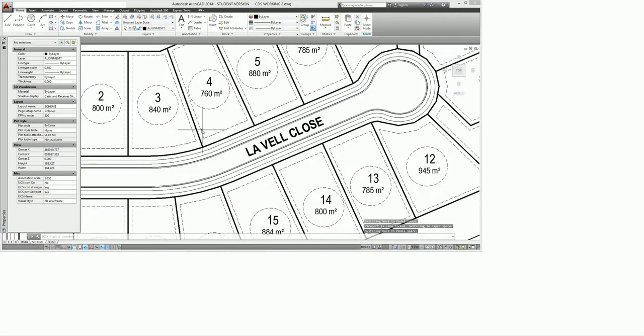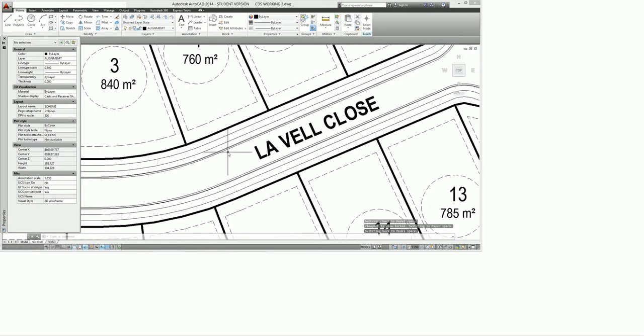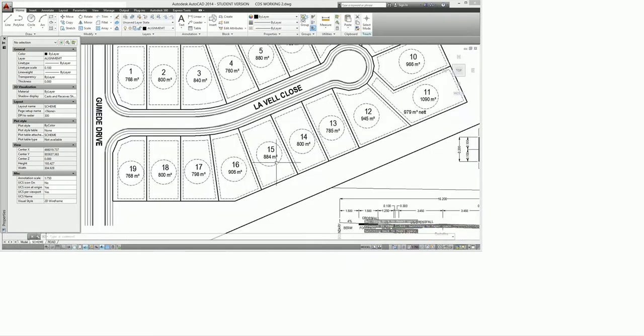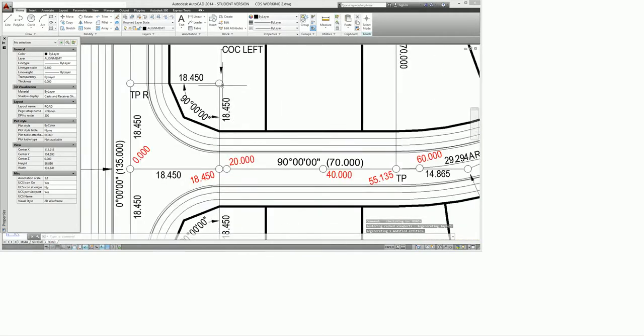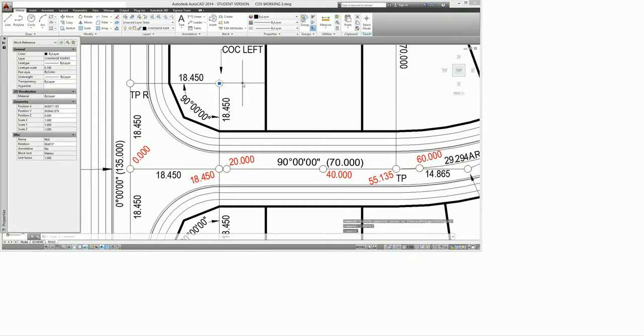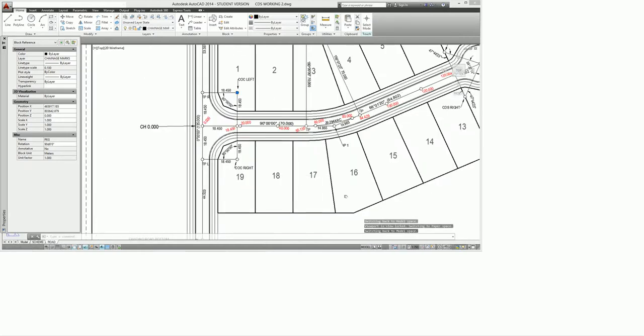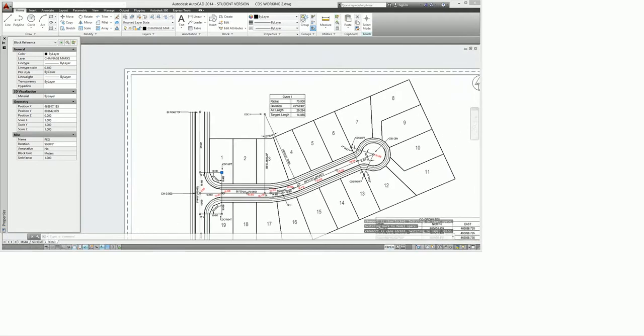Sometimes it's necessary to move the marks around a little bit from different layers. If we go back to the roading plan here, I've got all of these marks, the little wipeouts that I've used, and I've put those into a little block reference called PEG. I've created a block, but they're all chainage marks, so I will have to change some of those to another layer at a later time if I just want to show the chainage marks on the centre of the road and not these peripheral ones here. But I'll do that as I go along, just having them in different layers.